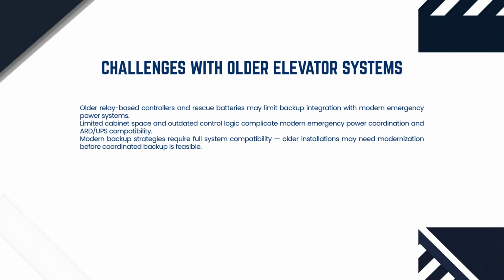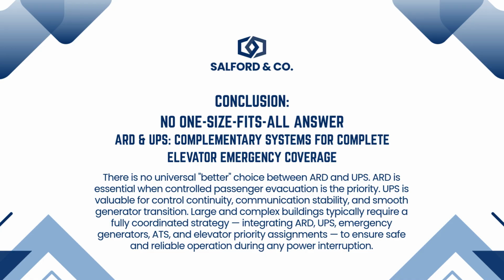Are we dealing with a new project or modernization? Does the old control system support modern backup coordination? These questions matter because older elevator systems may have relay-based controllers, aging rescue batteries, limited cabinet space, or control logic that does not integrate easily with newer emergency power systems.